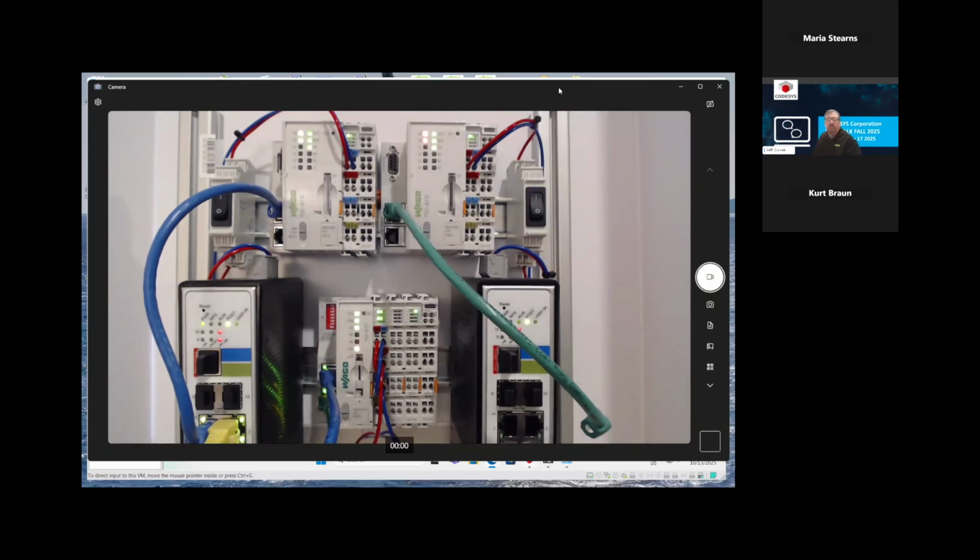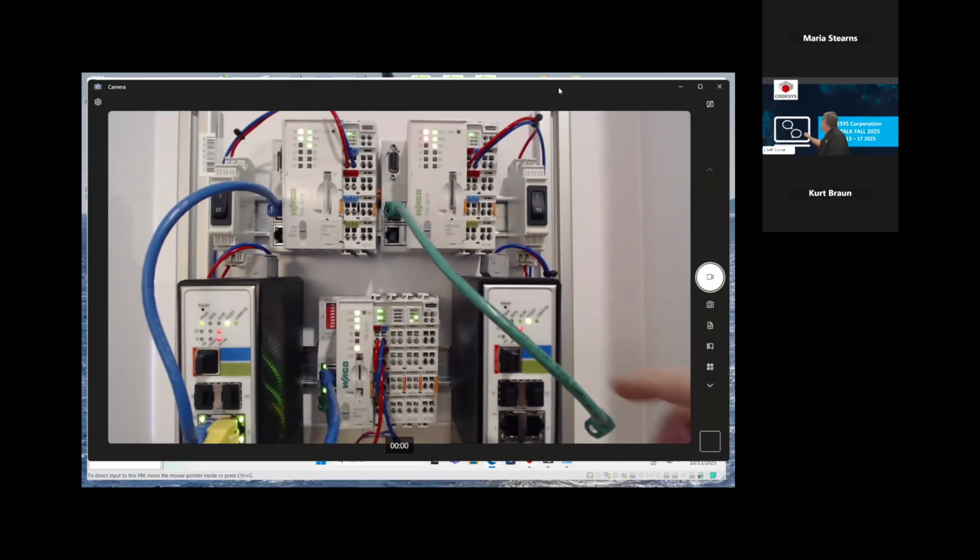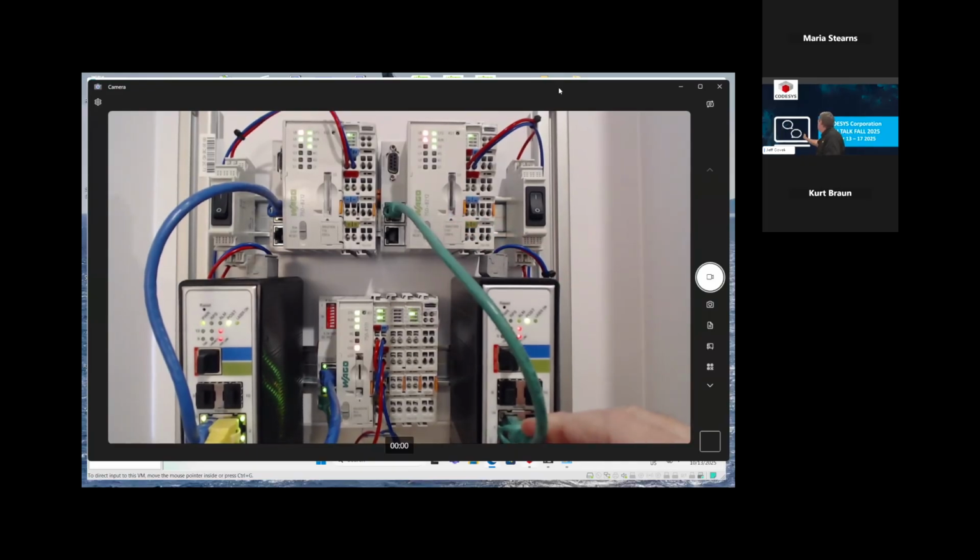So this one, he's lost sight of both the smart coupler and the other master. So he thinks he's in standalone because he doesn't see anybody else, but he also doesn't have visibility into the smart coupler. So he knows that something's up. So still the top one is yellow. He's lost sight of the other master, so he's operating in standalone. So okay, the other master is gone, so I'm just going to operate as a single PLC now. Put him back in. So you can see it just took a couple seconds to recover.